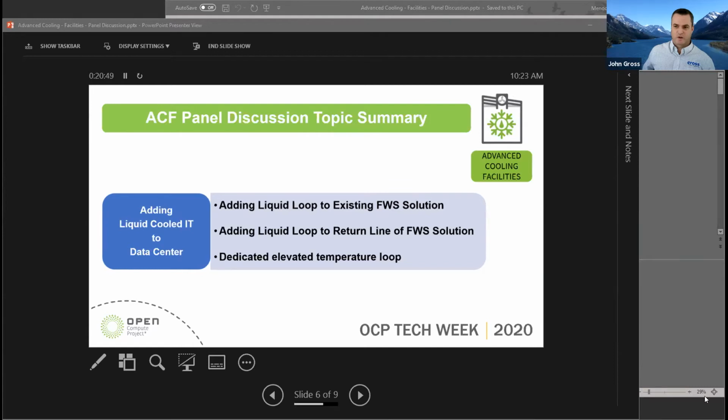Yeah, so I had a conversation in the last couple of days because, as Valley mentioned, the W classes is being actively reviewed right now by those within ASHRAE TC99, and he mentioned W32, W40s, et cetera. So there's an effort going on right now, not just to improve the granularity of the solution, but also to make it more meaningful to folks. And so what's being proposed right now, but it's not agreed upon yet, is actually ditching the 1, 2, 3, 4, 5 and actually replacing it with the temperature that's at the high end. So what's currently W1, which is 17C, would become W17.